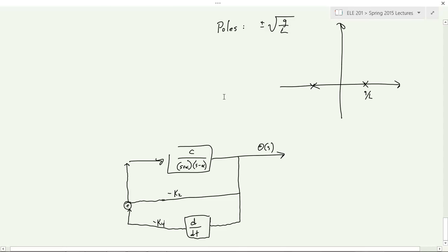So the other thing we can do, but we're out of time, is I'll go ahead and shut it off. The other thing we can do is we can additionally use the position sensor to keep it in the middle, or we can get it to track a position. I'll just turn that on as we end the class so you can see what that looks like when it stabilizes itself in the middle. And again, the way we do this is we do another control loop using position, and we use proportional and derivative in that control loop as well. So this time, it should try to stay towards the middle. And if you knock it away, it comes back.